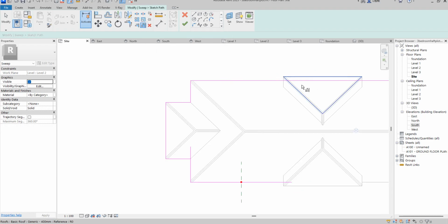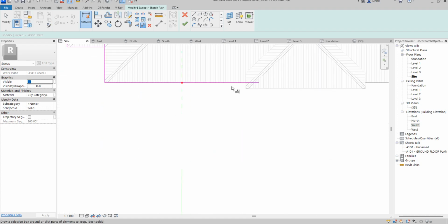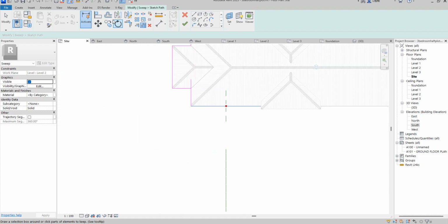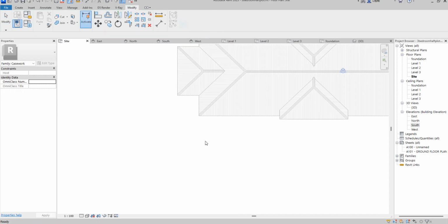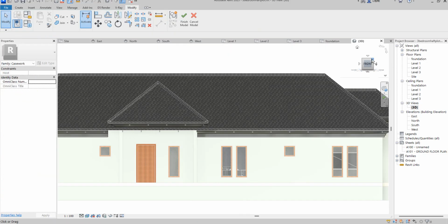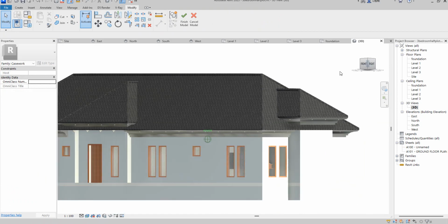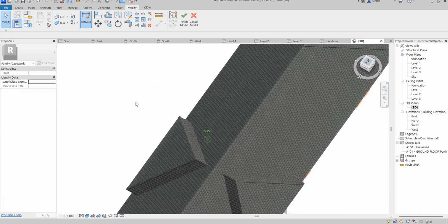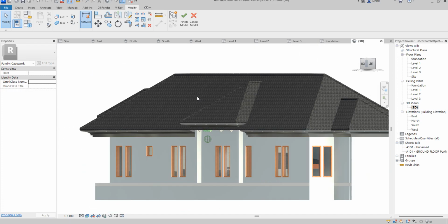So you finish it off in a clear way. Good. So I'm going to trim this one. I think with this I'm okay. So click finish and everything is joined. So you got this one in 3D and the whole thing is in place. So you see the concrete fascia going around, going around, going around. So that is how you create a concrete fascia.